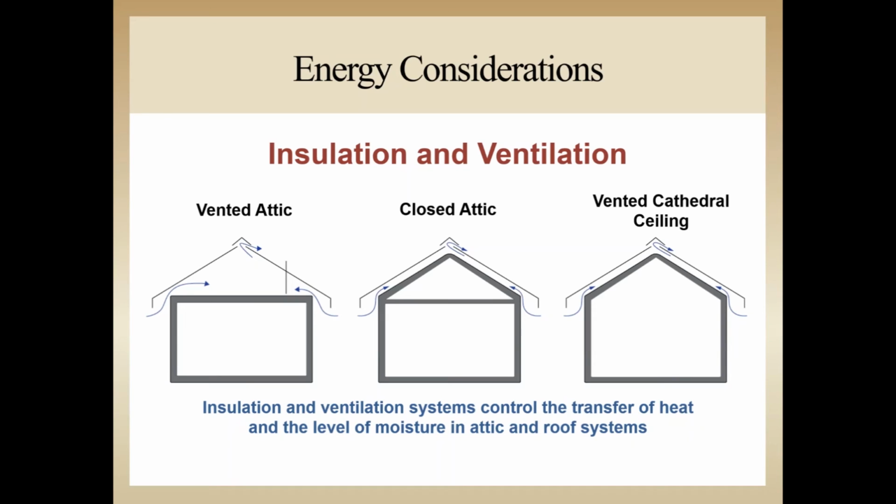Roof ventilation systems not only keep attics cooler in the warmer months, but they also facilitate air movement over cooler surfaces, such as the bottom of the roof sheathing and roof rafters, which minimizes moisture condensation. This air movement promotes drying and carries moisture outside through the upper level ventilation devices. It's important that I-joist roof systems address not only the structural requirements of the building code, but also the energy and building science requirements as well.